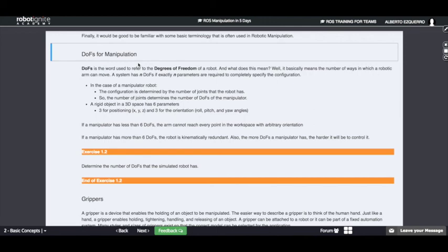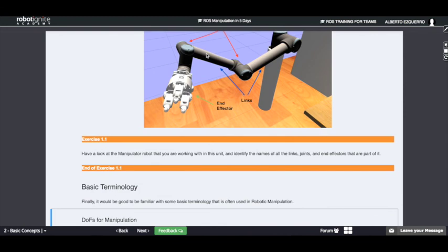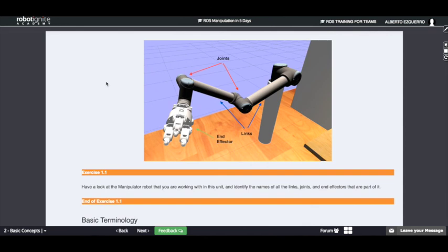On the other hand, for instance, the elbow, you can just move it up or down, right? You cannot move your elbow to the left or to the right, yes? So you can just move it up or down. Then we would say that the elbow has 1 degree of freedom. Each joint, of course, has its degrees of freedom, and depending on the movement the joints of the robot have, the robot would have a specific number of degrees of freedom.